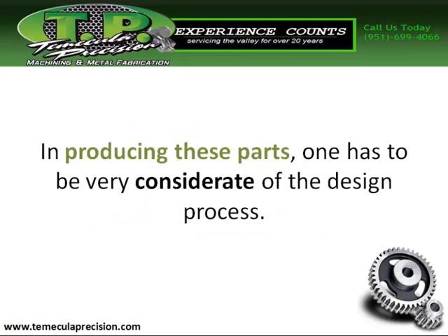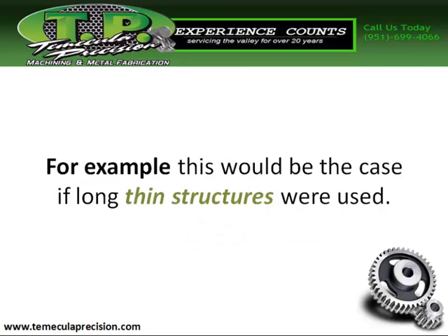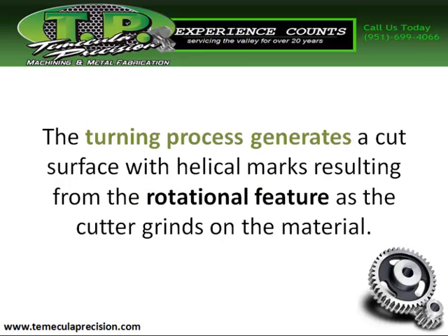In producing these parts, one has to be very considerate of the design process. Considering that the turning process applies a lot of pressure on the material, weak shapes that may involve flexing would be difficult to produce. For example, this would be the case if long, thin structures were used. The turning process generates a cut surface with marks resulting from the rotation as the cutting tool grinds on the material.